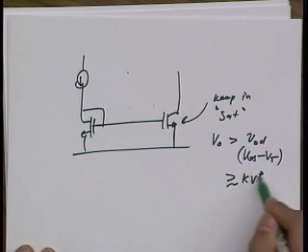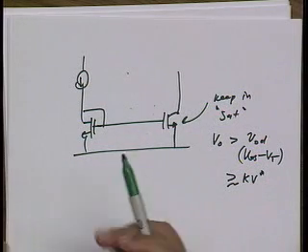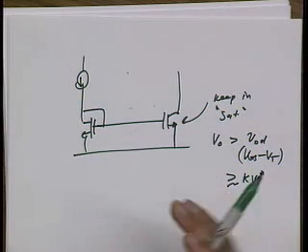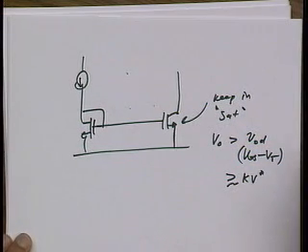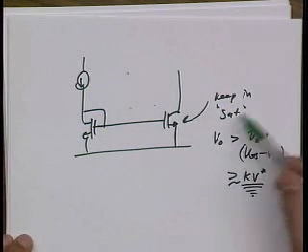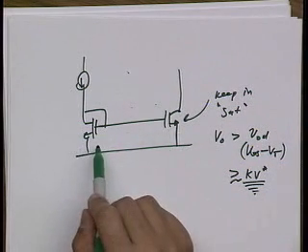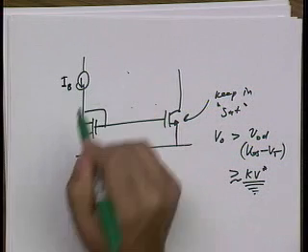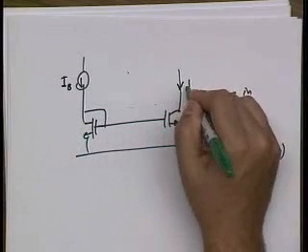Because in a modern transistor, the transition between saturation and triode is not so clear. What we really want is to measure the output resistance of this device and say, well, I know that if I'm, let's say, 1.5 times V star, the output resistance is high enough. In practice, we usually determine this experimentally using SPICE, but to keep this discussion simple today, we can just say V bigger than an overdrive voltage. Okay? What else? So how accurate is it? Well, we're going to talk about matching later. Basically, I have a bias current here. Let's talk about systematic error. What's the systematic error between the output current I out and IB?